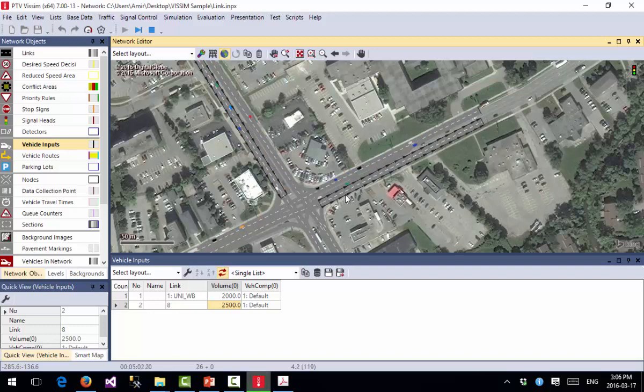You see here, they're all doing the left turn here, and here they all go right. No one goes straight from here. And the same happens for this one here as well. So this is the assumption of Vissim. Whenever they find a route, they will take it. So you need to define some routes before. You need to define the OD matrix or something like that, or dynamic routing, or you need to define constant values there.